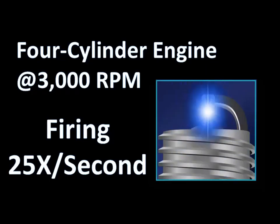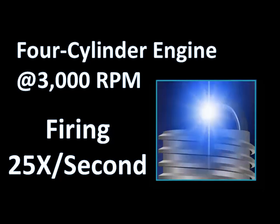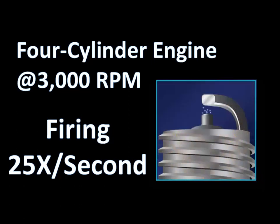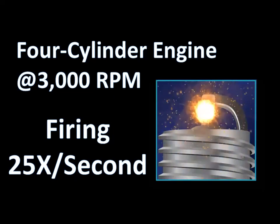Proper ignition system operation is extremely important to obtain satisfactory engine performance and fuel economy. In a four-cylinder engine running at 3,000 RPM, or revolutions per minute, each spark plug is firing 25 times per second. A considerable amount of intermittent spark plug misfiring can go undetected because of the very rapid spark plug firing.